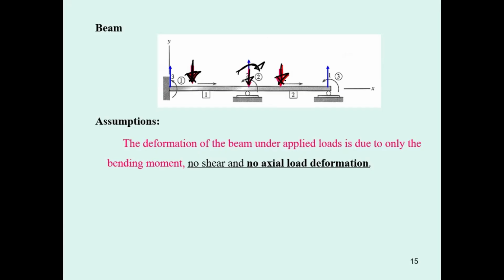Okay, and then you will use the fixed end moment and fixed end shear, and use the third law of Newton, applying from the end of the member to the nodes.